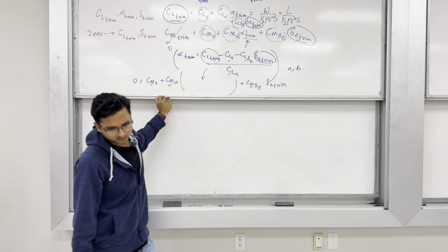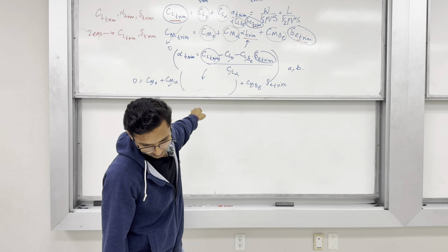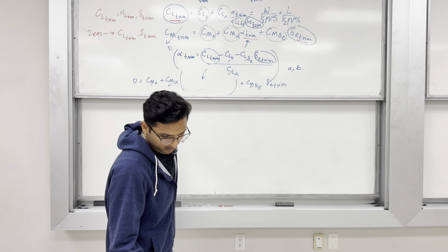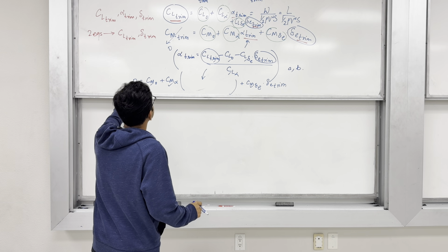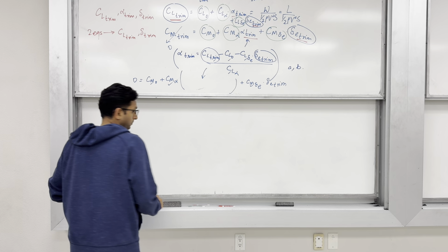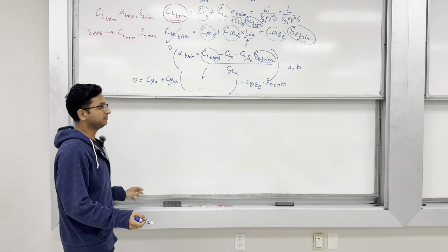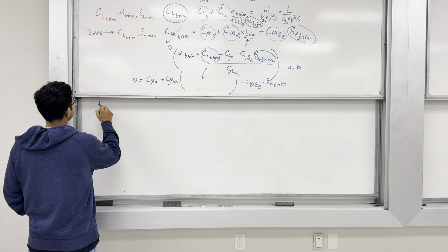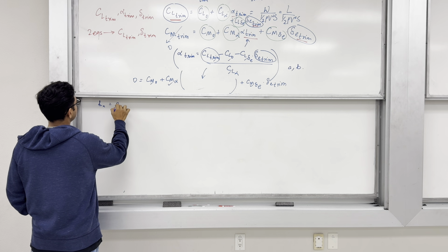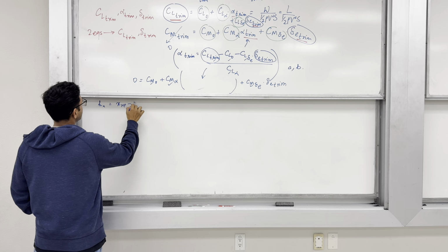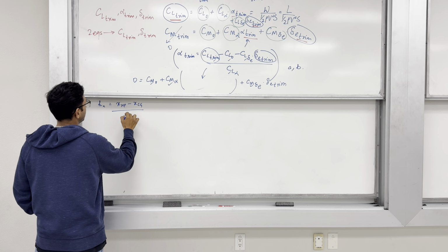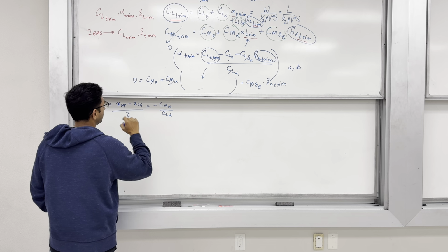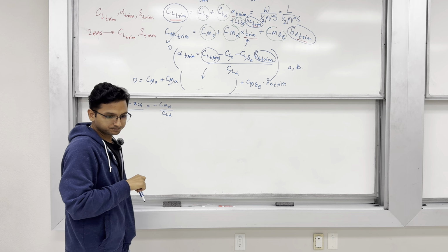Then moving on, the next part, find the most forward CG limit for a maximum alpha of 10 and deflection ranges for the elevator as given. So, whenever CG limit is being talked about, the first thing that we go and write down is the static margin. So, static margin is given as neutral point minus CG divided by C bar, which is also negative CM alpha by CL alpha.